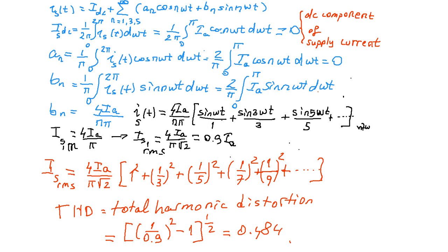Going back. Is Fourier analysis alright? So the square wave is analyzed and it is obtained that it is actually a combination of a number of different frequency sinusoidal waveforms. The fundamental one has the same frequency, but the third harmonic has 3 times higher frequency compared with the fundamental.